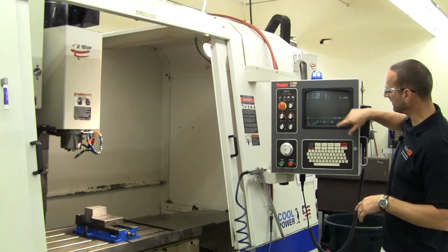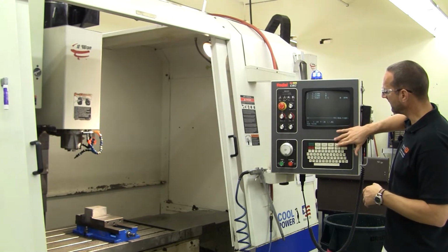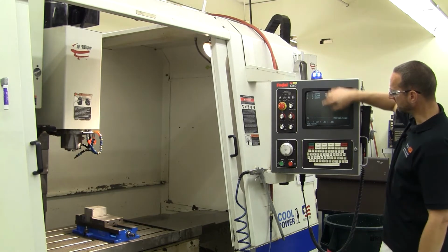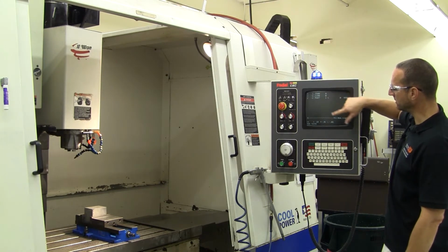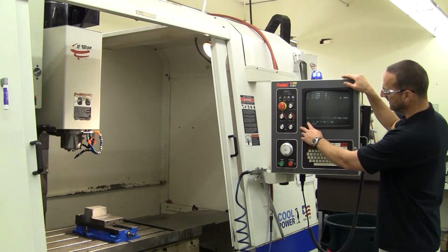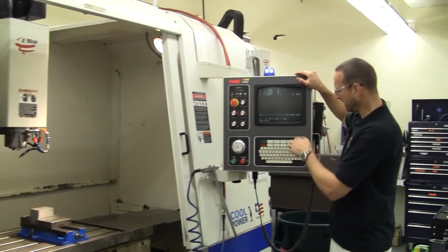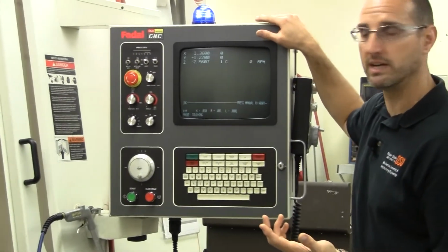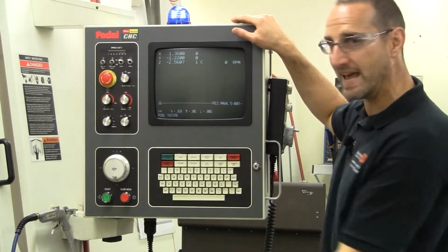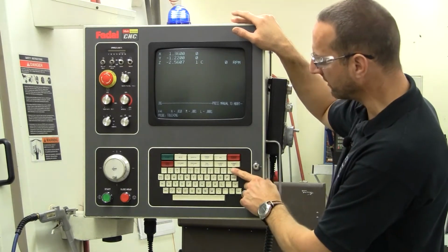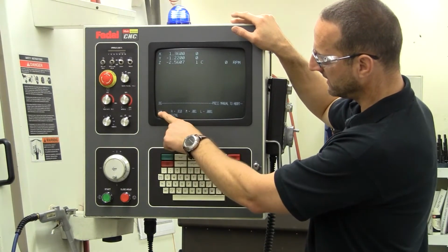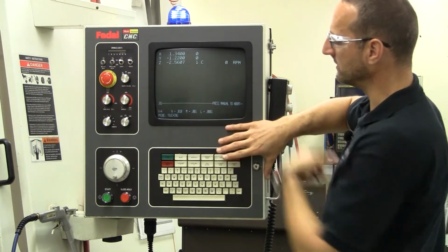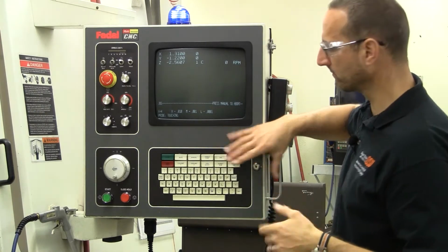So if I just want to incrementally change where I'm at in X, I can just hit the jog button one time, and you'll notice that I have changed by my increment size in the direction that I'm currently at. So I have X, I have the plus key, and if I push the jog button, I move positive 1/10,000th of an inch. If I want to go negative, then I just hit the minus key here on the keyboard. The indicator should change to minus, and if I hit the jog button once, now I'm stepping down, or moving in the negative direction.